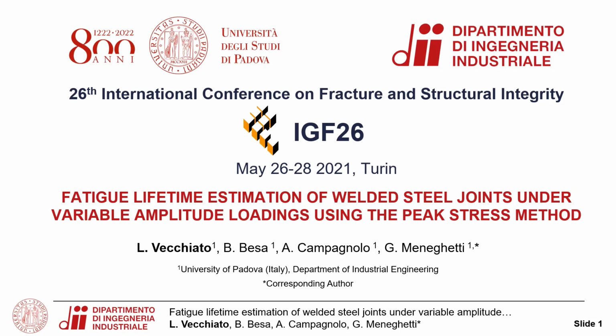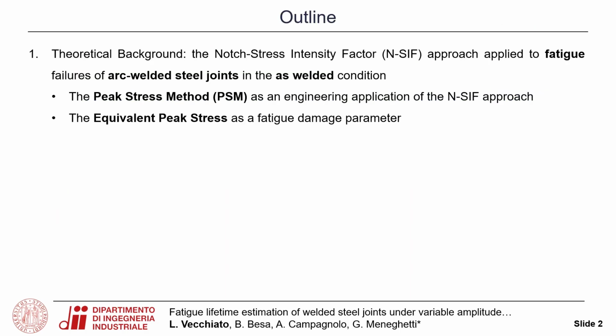Today, we'll present a work on the application of the peak stress method for estimating the fatigue life of welded joints subjected to variable amplitude loading. The presentation is divided into four sections. The first one is a theoretical background on the peak stress method and on the equivalent peak stress concept, which represent an engineering application of the notch stress intensity factor approach applied to fatigue failures of arc-welded steel joints in the as-welded condition.